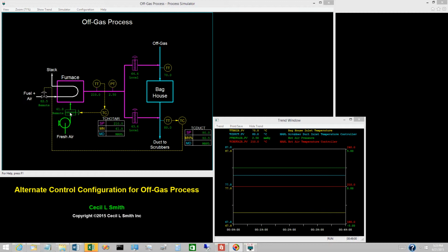Which of the final control elements is most appropriate for controlling the scrubber duct inlet temperature? Suppose all other control variables, that is, hot air pressure, hot air temperature, and baghouse inlet temperature, are maintained at their targets. To increase the scrubber duct inlet temperature, the heat input rate to the furnace must increase. This suggests pairing the scrubber duct inlet temperature with the fuel gas valve.